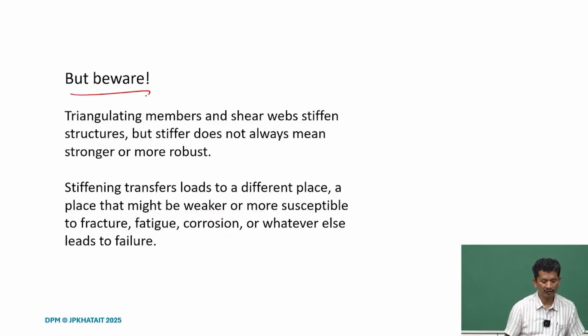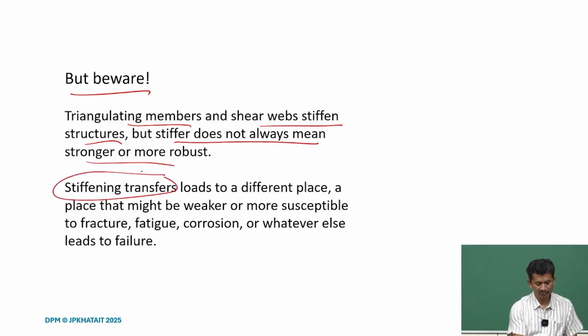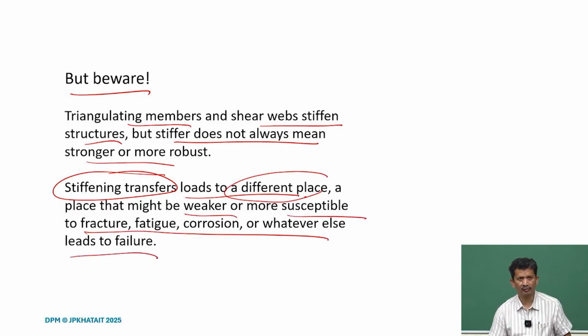But be aware, triangulation does not mean it will solve every purpose, right? It will definitely stiffen the structure, but it does not always mean stronger and more robust. Why? Because when we stiffen the structure, it transfers the loads to a different place, right, and that may be weak, or susceptible to all kinds of fracture, failure, corrosion.